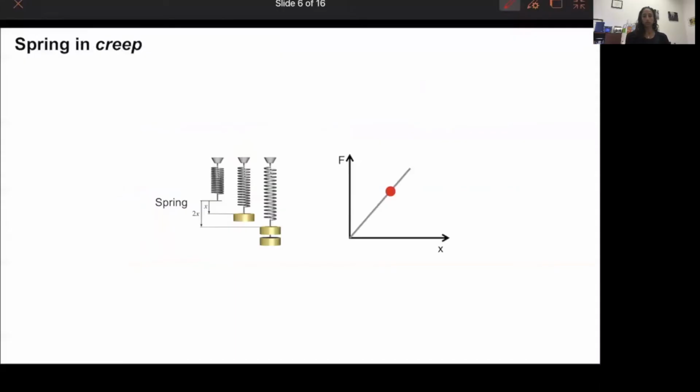In creep deformations, we're talking about time-dependent responses. Now, we start with the materials that we're more familiar with, how they might respond in creep. If we apply a load and we hold it, we know that we're going to get a certain displacement. So we apply a force at some rate of newtons per second, and we're going to get an output. Our reading, our output will be displacement. So we refer to this as being force controlled because our force is our input.